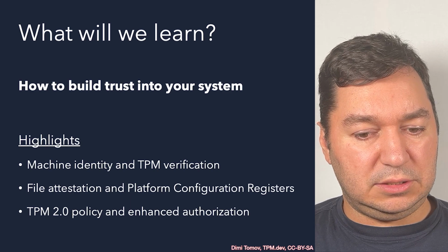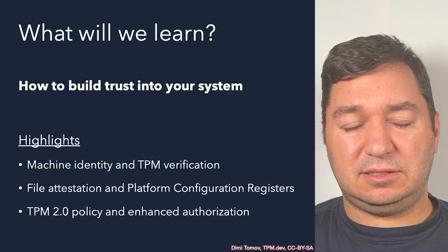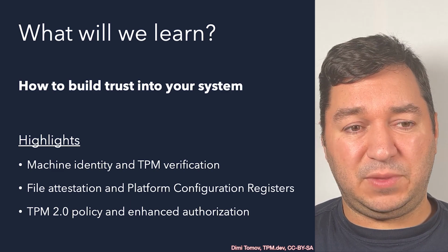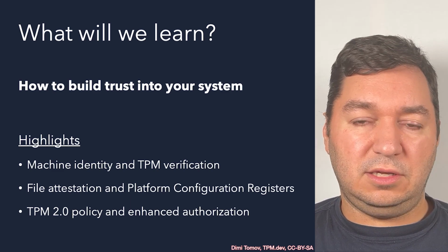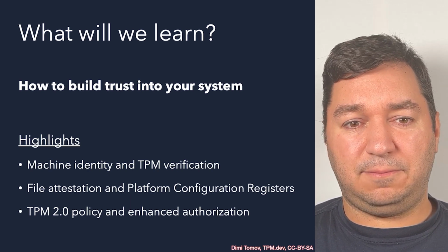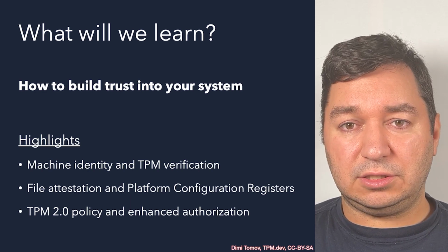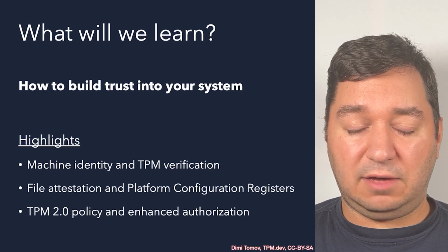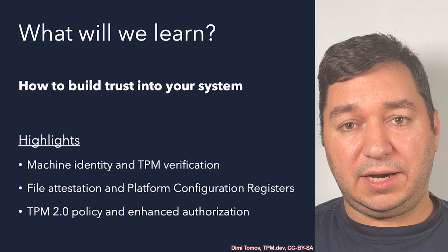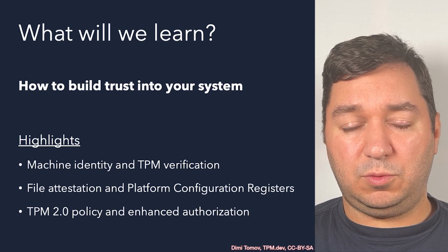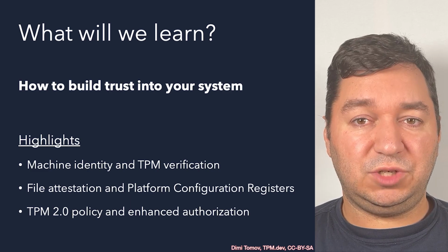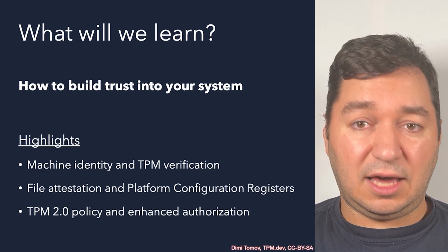I think with the rise of connected devices throughout our home, throughout the industry, throughout our streets, in the cities, and in the cars nowadays, we need to talk about machine identity and how the TPM is a great tool to achieve that. We need to talk about TPM verification, how to prove that the TPM we have on the system is genuine. It has been manufactured and provided by the TPM vendor who produced it. And through there, establish a root of trust that will allow us to build machine identity that is unique to the system having that TPM.